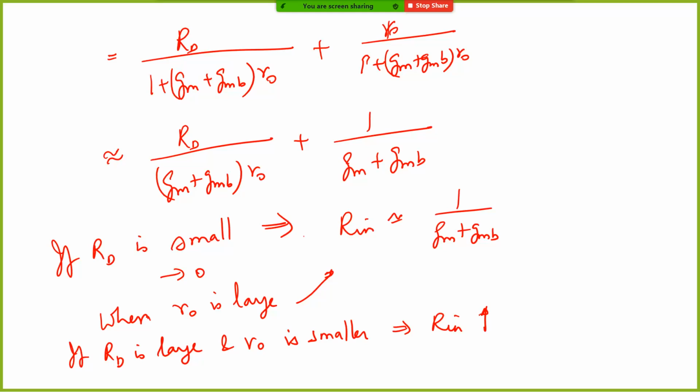When you have very high frequency signals passing there, you use a 50 ohm transmission line, and we all know from our microwave theory that the load impedance should be equal to the characteristic impedance of the transmission line. Only then will you not have reflection, only then will you have maximum power transfer, right? So for those applications you need an input impedance equal to your characteristic impedance. For many of our RF systems, the characteristic impedance is nominally taken to be 50 ohms.